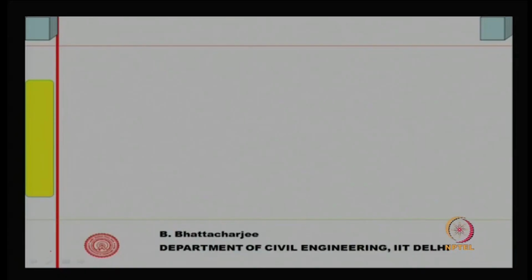We defined what pozzolana is, and then we tried to classify them, naming the main ones: fly ash, granulated blast furnace slag, metakaolin, rice husk ash and silica fume. At the extreme end, silica fume is the finest, most reactive, and contains the maximum amorphous silica, but in the Indian scenario it is the costliest.